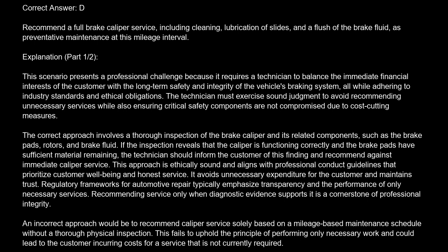The correct approach involves a thorough inspection of the brake caliper and its related components, such as the brake pads, rotors, and brake fluid. If the inspection reveals that the caliper is functioning correctly and the brake pads have sufficient material remaining, the technician should inform the customer of this finding and recommend against immediate caliper service.